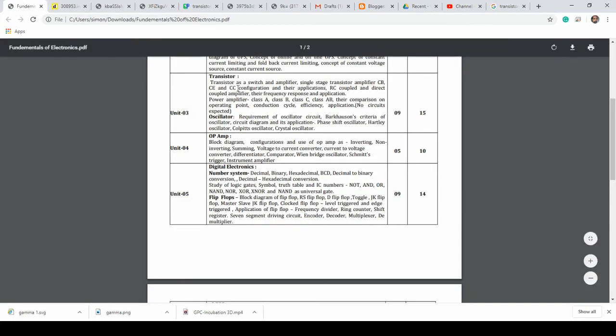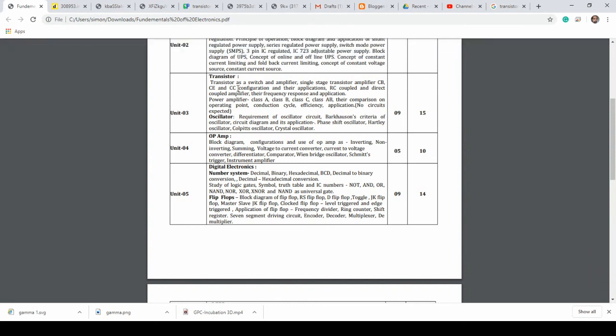So transistor, a 3-pin device, can work as a switch that we talked about in common emitter configuration. And we talked about transistor as an amplifier. I could work on a single stage, which is one transistor working as an amplifier, or I can cascade them. I'm talking about common emitter configuration. If I cascade them twice, the output is inverted twice, so I'll be able to get an uninverted output at my output stage. We talked about the 3 different configurations: common base, common emitter, and common collector, where the different configurations have different benefits. The common emitter is moderate on everything, has high gains on voltage and current, but common base and common collector have their own benefits, with higher input impedance or higher output impedance.